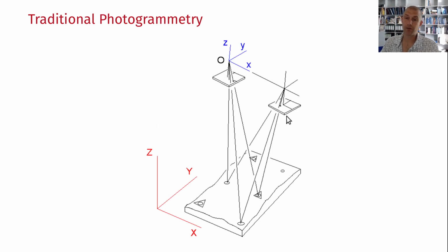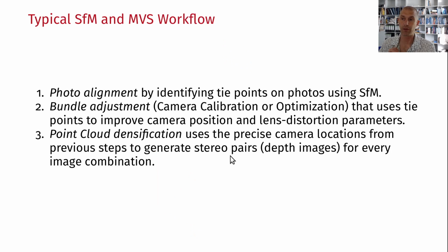I'm going back here for the traditional photogrammetry. If you have aerial photogrammetry, you usually end up collecting or hand clicking 8 to 12 markers and tie points per pair. That's much fewer points than you identify via the structure from motion method.